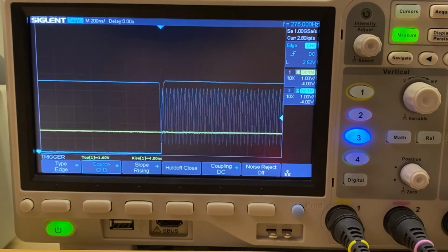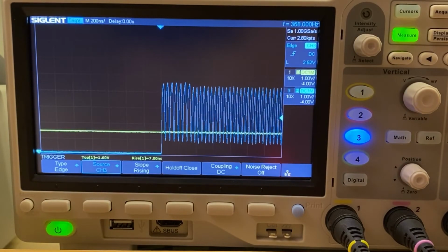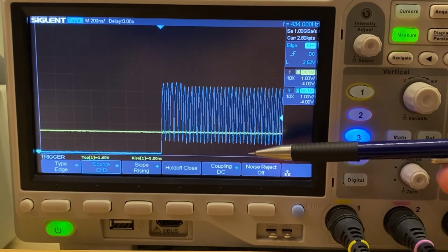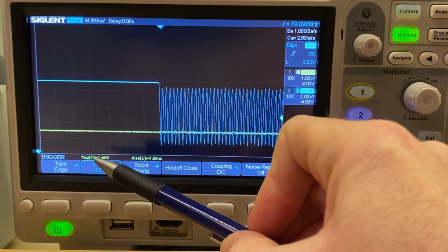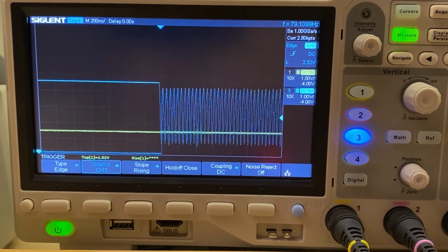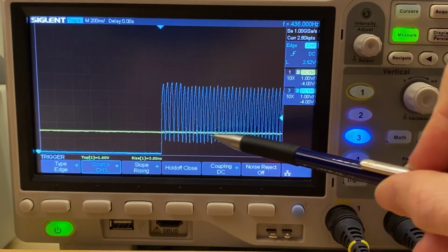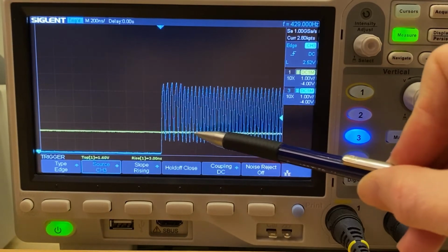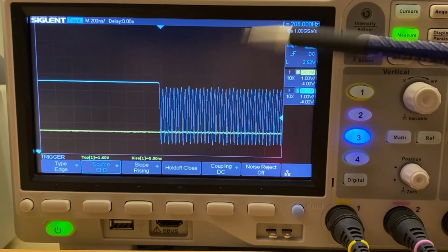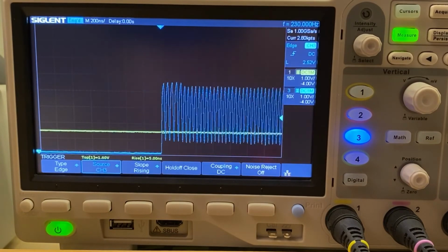And the problem is because our clock is rising so slowly, it gets confused, and it doesn't know what to do. Right now you can see the yellow trace, it's about 1.5 volts, and for this particular chip, that's the dividing line between a high and a low signal. Normally you want your clock signal to shoot right past that dividing line and make it clear, but since it's going very slowly through that dividing line in this up close view, the output of the counter is confused, and it's just going up and down because it doesn't know what to do, and it's called a metastable state.